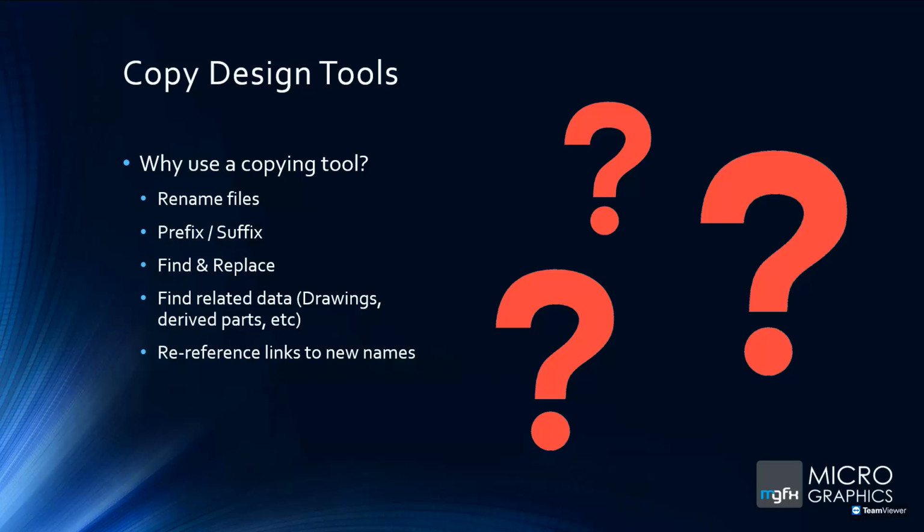One thing with the iLogic copy option is that you had to select the drawings and it found all the children. One thing I didn't mention about Vault is you can pick a part or an assembly and it will find the parents. So if you copy a part or an assembly, it will find the drawings and copy the drawings automatically.